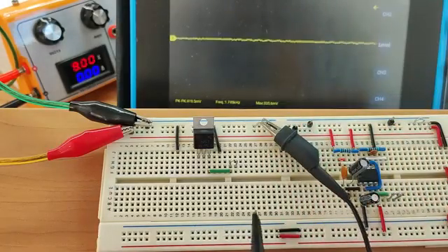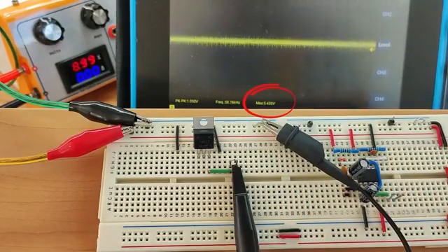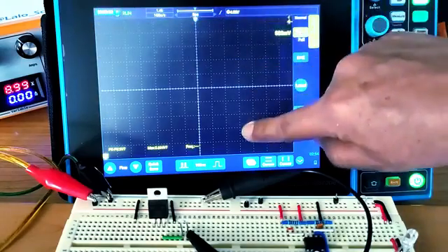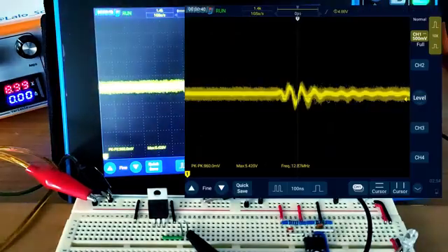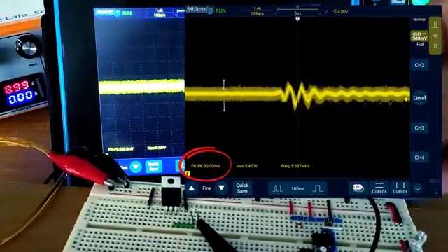If we look with the oscilloscope, indeed it appears around 5 volts. Good. But if we look close there, the line looks fuzzy. This is electrical noise, mainly generated by the power supply, but also by the regulator itself, internally switching at high speed trying to stabilize the output voltage. This noise includes a ripple, seen as a high-frequency AC component superimposed on the DC signal, which can cause problems in certain applications, in this case more than 900 millivolts.